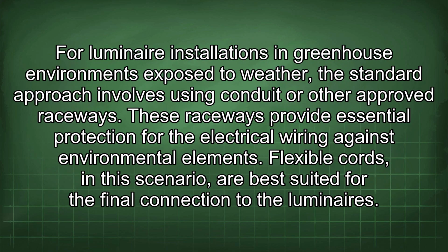For luminaire installations in greenhouse environments exposed to weather, the standard approach involves using conduit or other approved raceways. These raceways provide essential protection for the electrical wiring against environmental elements. Flexible cords, in this scenario, are best suited for the final connection to the luminaires.